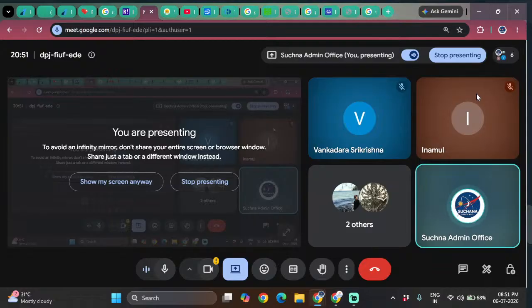Actually I needed to tell about ground planes today and close the session today itself, but I wanted to tell you something more interesting. That's why I told about visual inspection, thermal analysis, heat sinks, and the rules. Adding gold fingers itself is out of our schedule, but still I told you not only about gold fingers but how to add chamfers. The practice is a 45-degree angle. And I told you a couple of rules: silk screen layers not allowed, soldering. All these things we discussed today.